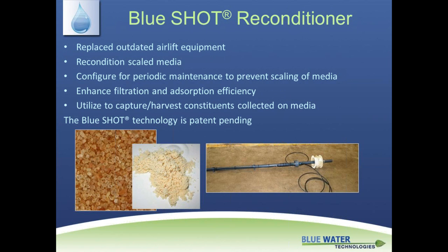That's what we saw in the industry, many decades past, with static media filters, where there's no process control to inhibit scaling, etc. So Blue Water actually came up with a process for scale removal and to inhibit scaling that fits within the vessel. That's a continuous process, does not require any additional interaction or oversight from the operator.